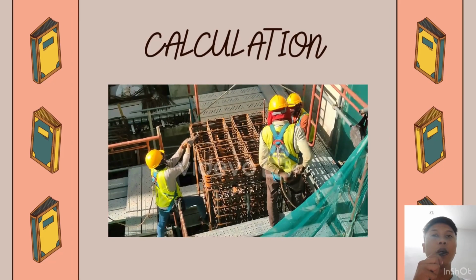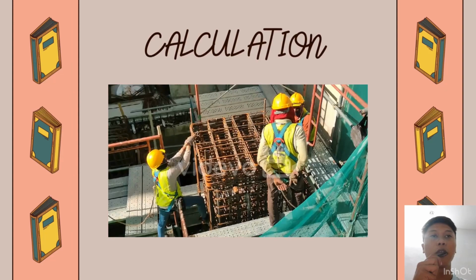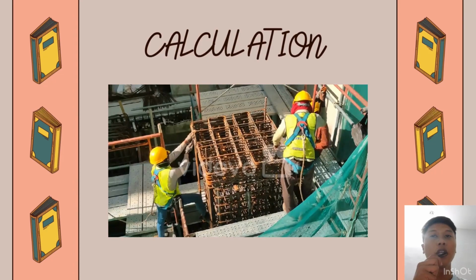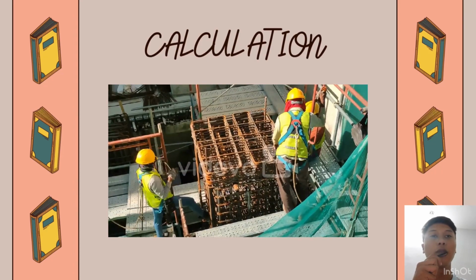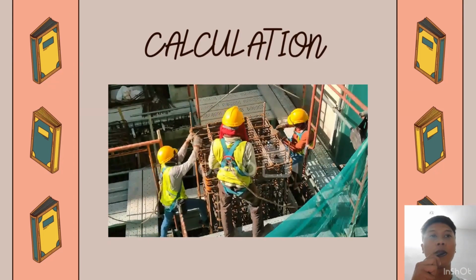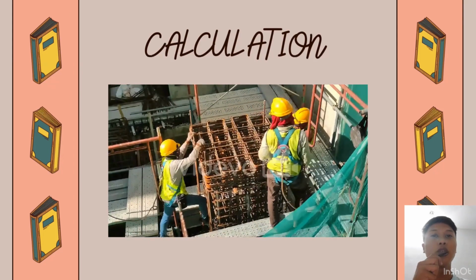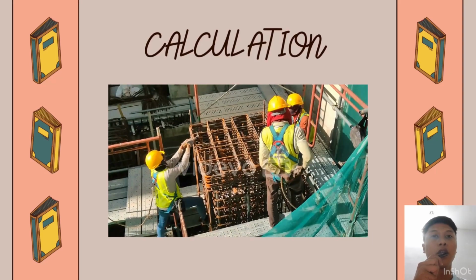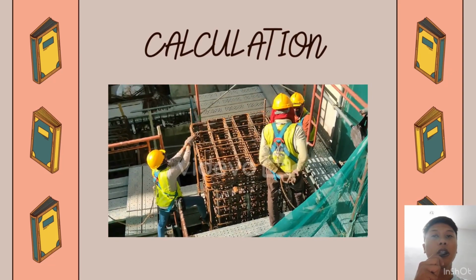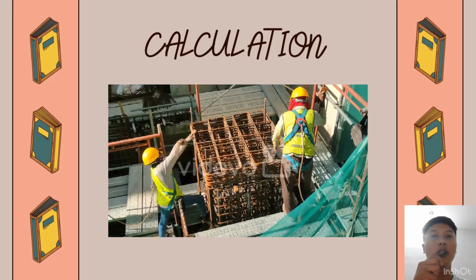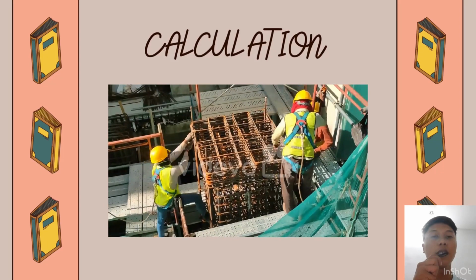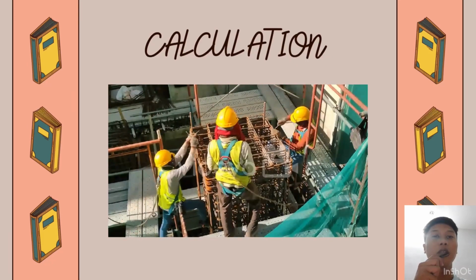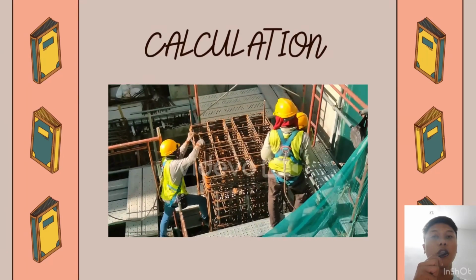As for today, I'm going to present the calculation part. So for this project, our group has chosen Lagrange method in solving a real-life problem. For our project, we want to estimate the closest tensile strength that should be reached in order to have the minimum yield strength needed for reinforced concrete, also known as RC. This is important as any complications due to the unfit and unsuitable type of steel will lead to a catastrophic failure to the structure. For a typical type of RC, the reinforced steel is required to have 40,000 up to 60,000 psi of yield strength. By using the Lagrange method, we want to estimate the minimum tensile strength needed to have the minimum strength of 40,000 psi.